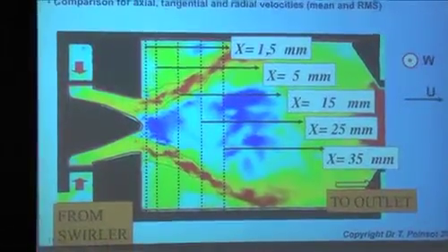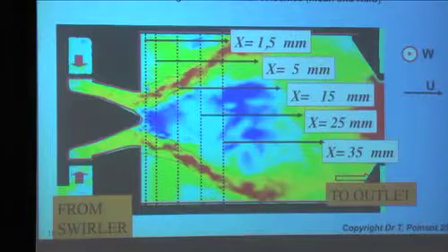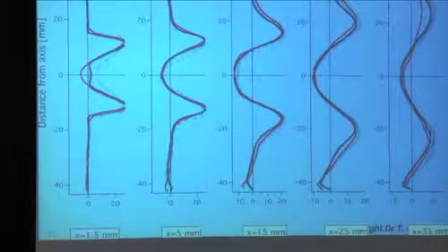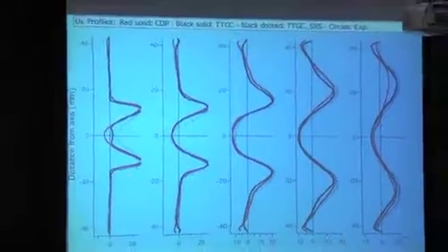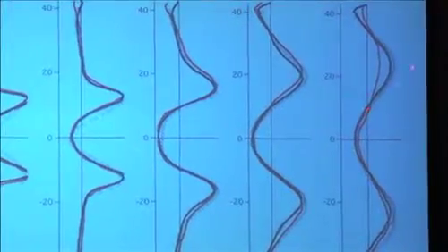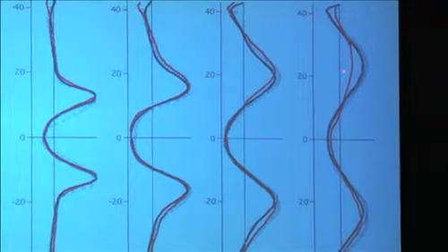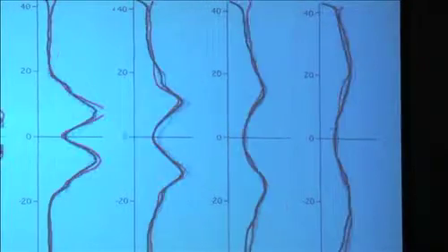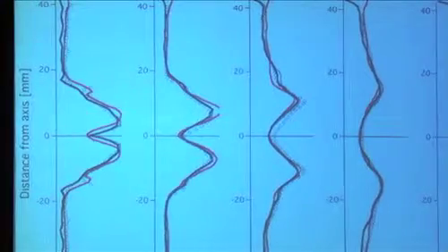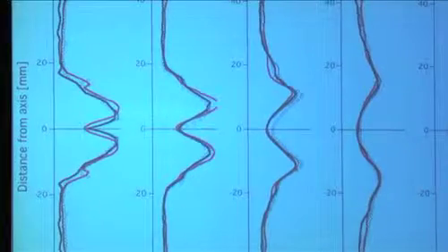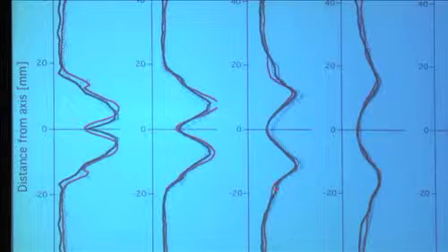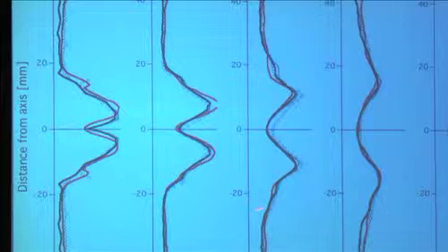And this is a burner where the injection is really the one you have in an engine. So this is really very close to engine conditions. Apart from that, you see that LES is doing rather well everywhere, capturing the mean velocity profiles with precision. Of course, the French code is doing better than the American one. So this is when things get more interesting. This is not the mean velocity, it's the RMS of the velocity. So it's U prime as a function of space.